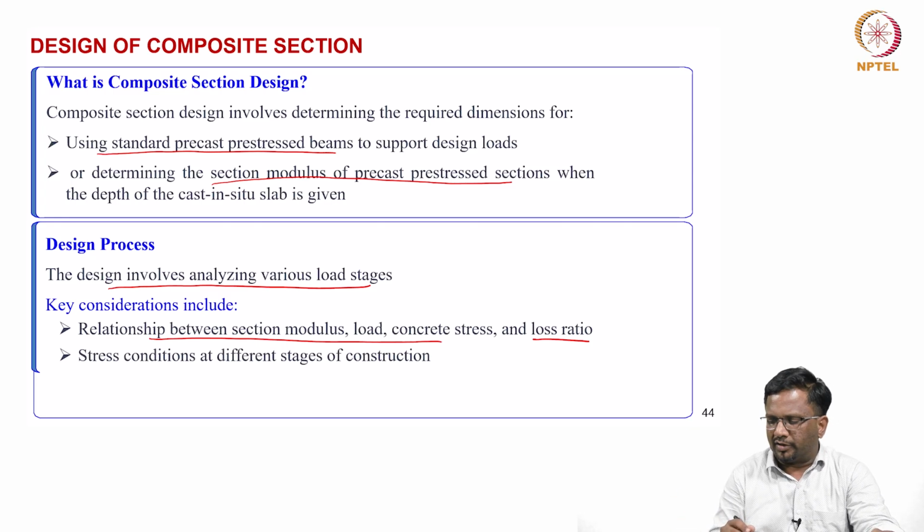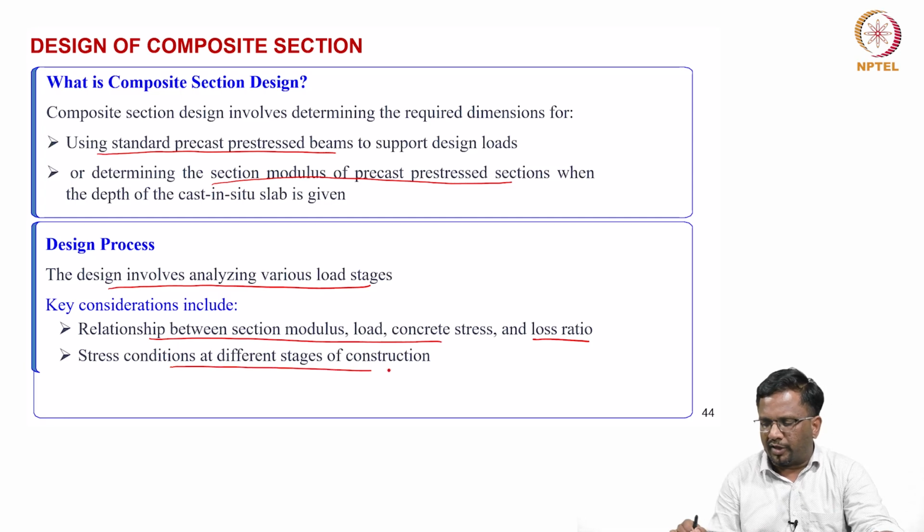And as we explained, we need to do the analysis for different stages of construction. In composite construction we have studied the stresses at the time of transfer of pre-stress, and then when the dead load of the cast in place slab is placed, depending upon whether it is propped or unpropped, how you do the analysis.